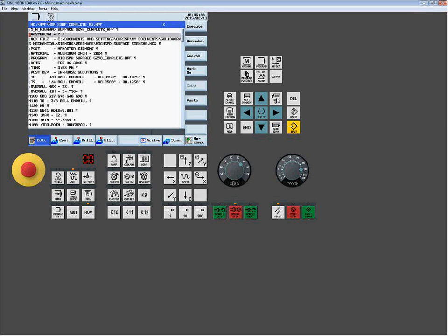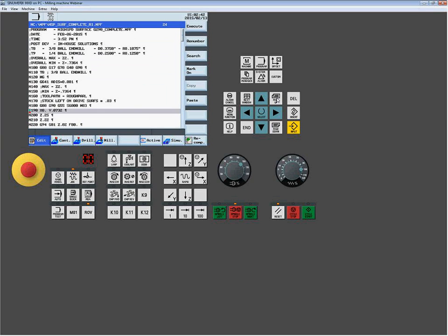Okay. So if I still look at the program, I can see different features. One of the first things I want to point out and show you, and you guys saw this command a little earlier, is this G641 ADIST equals. Now, that's actually a pretty old command. That's the corner rounding function that I earlier talked about in the slide we looked at with the G645. G645 is just a newer version of this function. We are always what's called upwards compatible. That means we always want to allow programs that were written for an older control to be able to run in the new system.